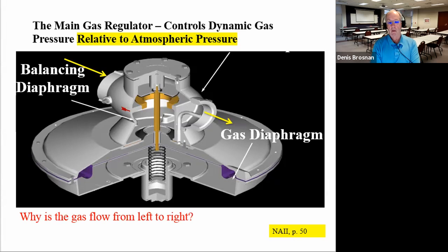But what a main pressure regulator is doing is controlling the flow. And so last time we talked about the gas coming in, and there's a valve that opens, there's a spring here and a diaphragm that's controlling the valve position. We don't see the whole diagram in this cutaway view, but it's pushing this valve open, and the spring pressure is helping this to happen.